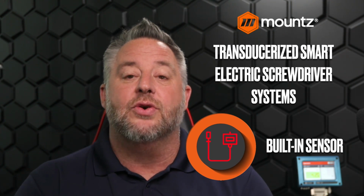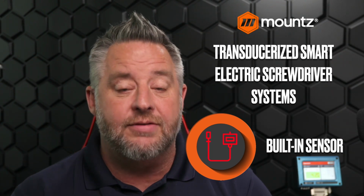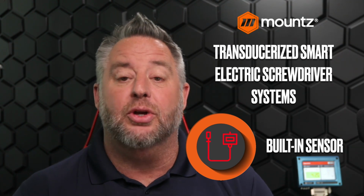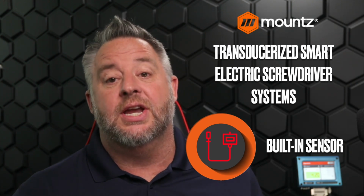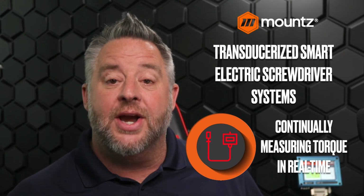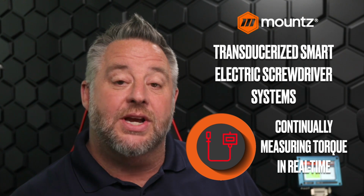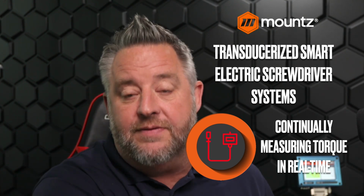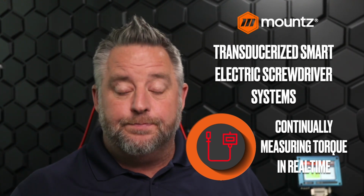Number 3 here is going to be using a transducerized electric torque screwdriver. And that simply means that there is a built-in sensor in the tool that is constantly monitoring the actual torque output that is being generated by the tool. This is done obviously in real time, giving us our ability to do our previous key, which was collecting that data.